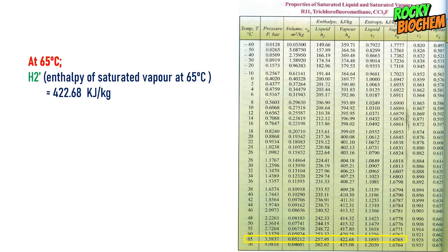After the saturated vapor enters the compressor, it is compressed isentropically and becomes a superheated vapor. So we have to remove some superheat from it before it enters the condenser. The point 2 prime is the point where the saturated vapor enters the condenser. At that point, we no longer take it as superheated, but rather just a saturated vapor.